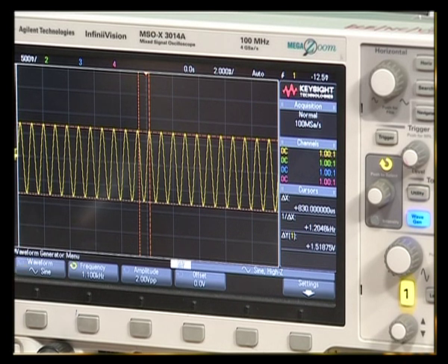So, as you go from 1.1 kilohertz to 11 kilohertz, the gain changes by minus 35 dB. Therefore, the roll off rate is 35 dB per decade, which is closer to 40 dB per decade. This roll off rate is verified, and we have also verified the cutoff frequency, which is 1 kilohertz, and the passband gain, which is 1.565.